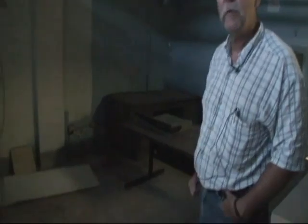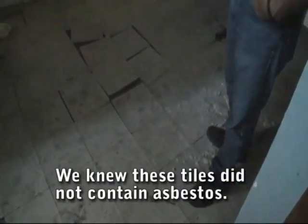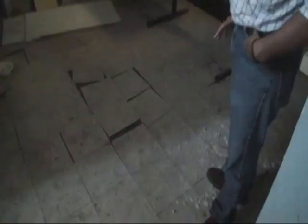Another common asbestos containing material that you'll find in buildings is floor tiles. There's many different sizes and colors of floor tiles. We're looking at 12 by 12 floor tiles. A general rule of thumb, 12 by 12 tiles typically are not asbestos containing, but every now and then you can find it, so you do need to make sure they're sampled. Another problem with floor tiles is the analytical technique. They're hard to analyze using conventional polarized light microscopy. It may need to be TEM'd or something, or point counted.